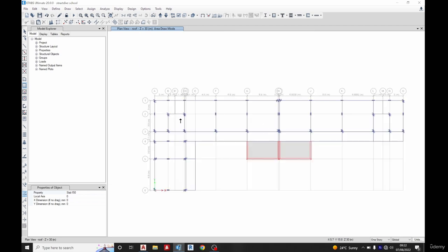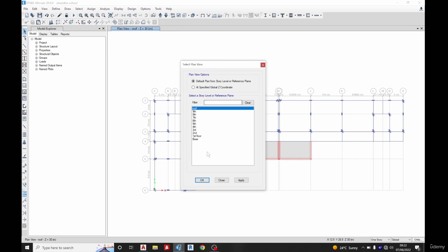Okay, so what we need to do now to also reduce the deflection along this rate is to put some critical shear walls here to make it stiffer, put another shear wall here to make it stiffer. What I'll do now is I'll just do it from the first to fourth floor, test if the shear wall is enough. So I'll go to the plan and choose first.